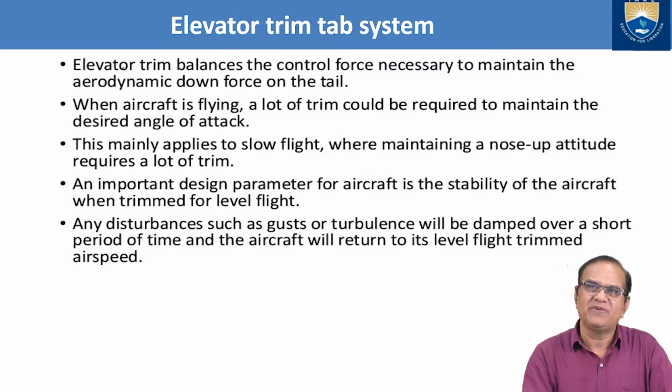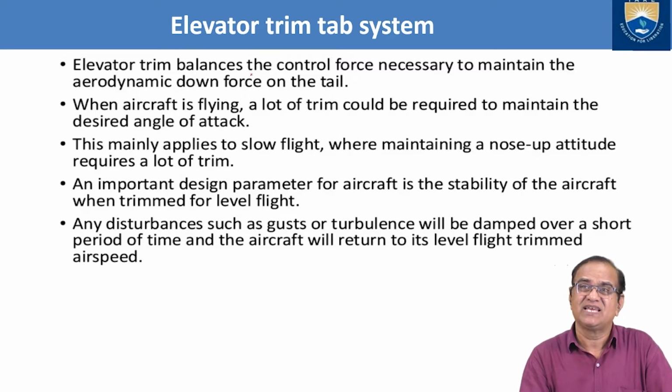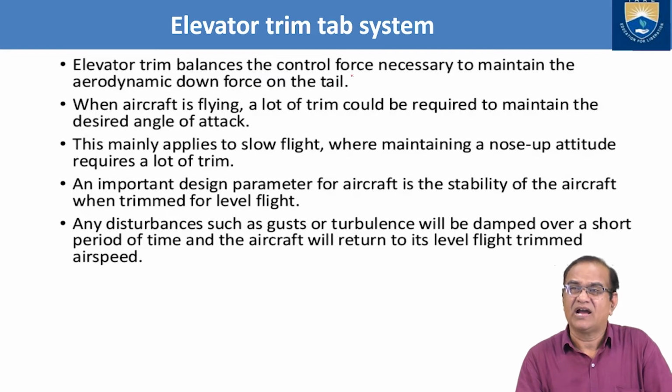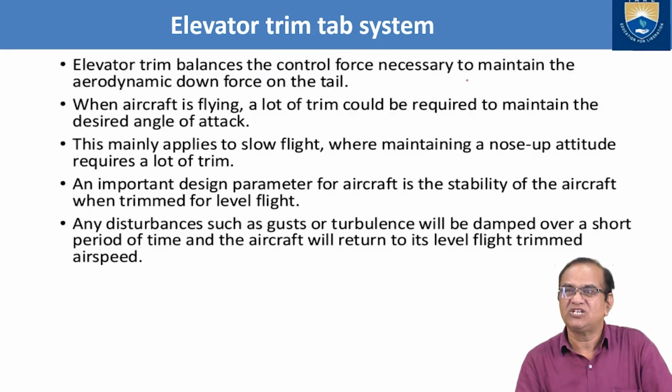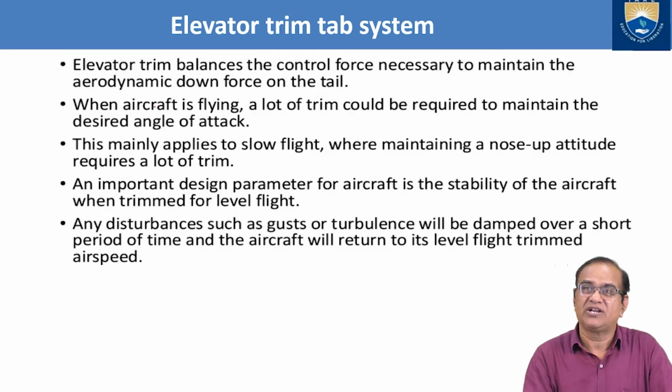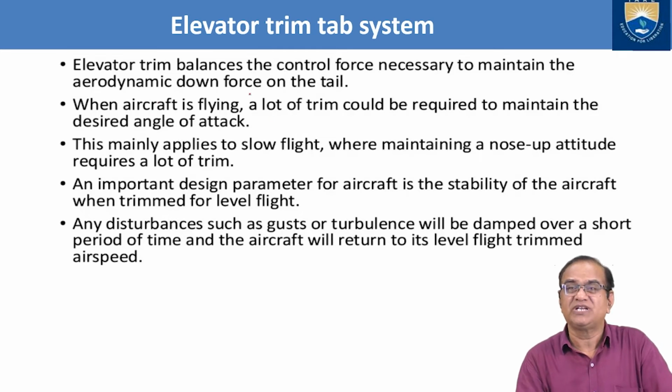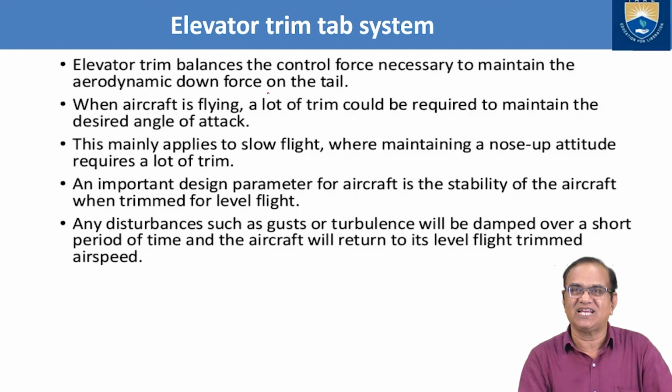So what is the purpose? Elevator trim balances the control force necessary to maintain the aerodynamic down force on the tail. So it is maintaining the down force on the tail.